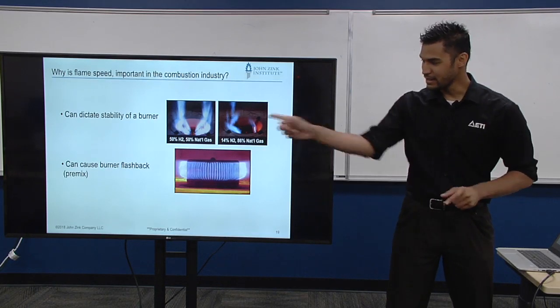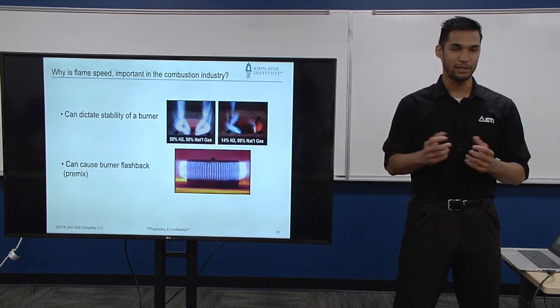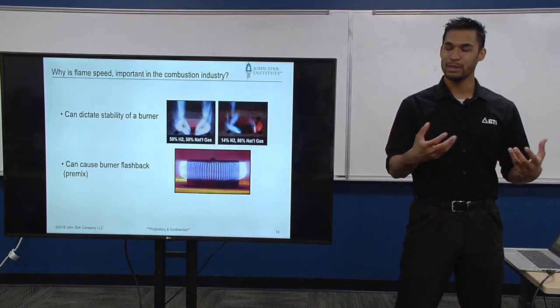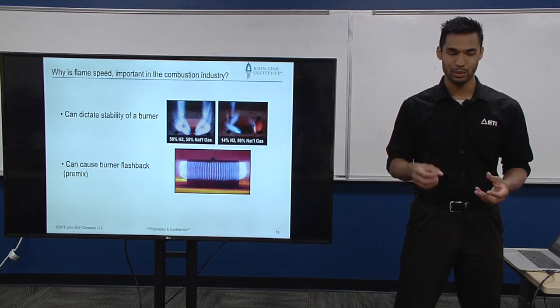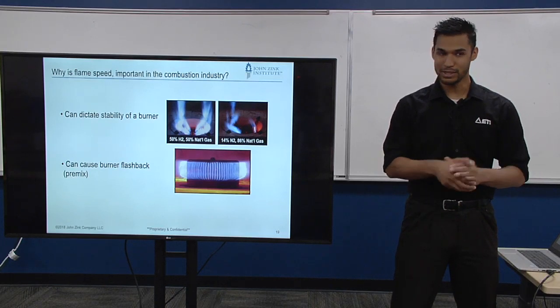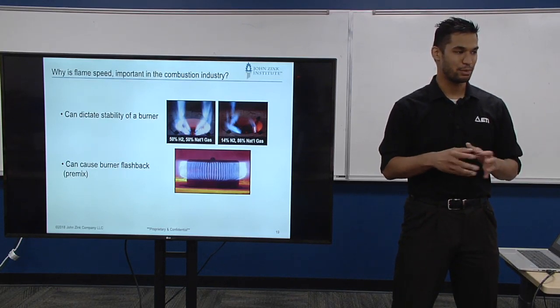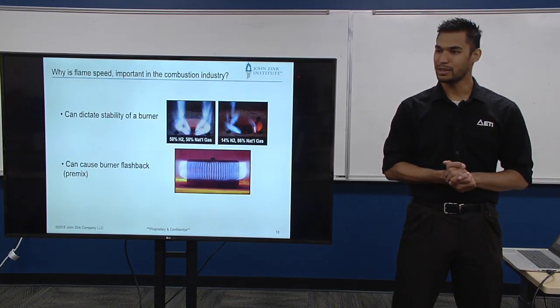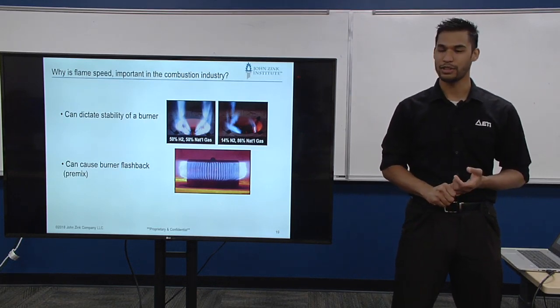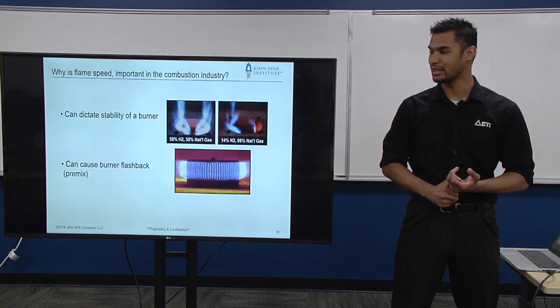No, because this side is burning good, but the other side, instead of combusting the fuel and creating non-combustible flue gas products, we're just shooting fuel in a box. And that can be very dangerous. You want stuff to burn, and you want to create CO2 and water. You don't want to just let gas fill up a room or a box or a furnace or whatever your process is, or a heat exchanger.